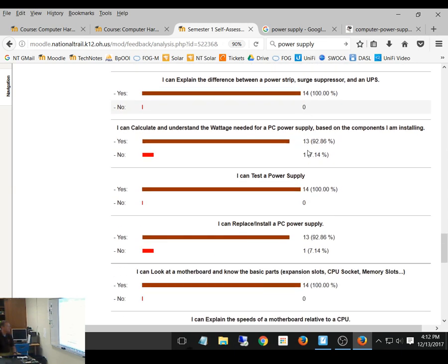Okay, so that's that one. I can calculate an extra wattage. That one's just a laundry list item. Just need to go through the components and remember the calculated versus minimum versus recommended, where we're getting the calculated, whether it's off the power supply calculator or after adding our laundry list together, rounding it up to the next 50 to get our minimum, and then adding 50 more to get our recommended. And realizing that I can always go larger. It's more efficient if I do. I just want to stay away from those minimum numbers.